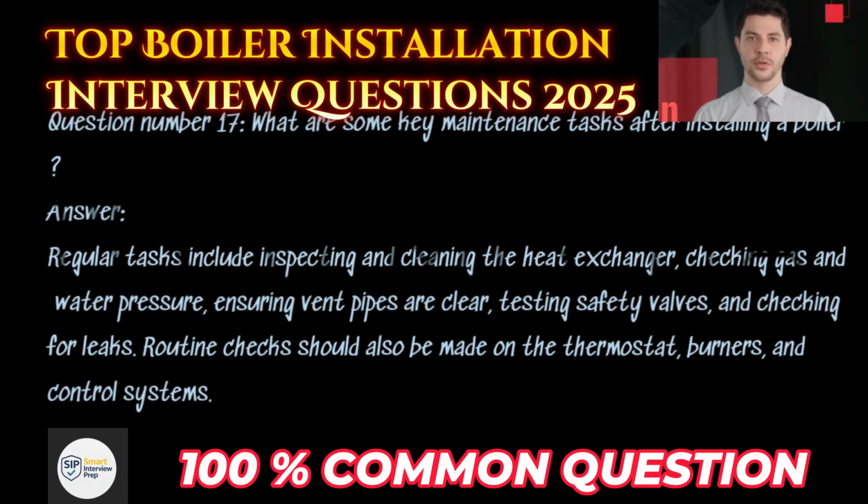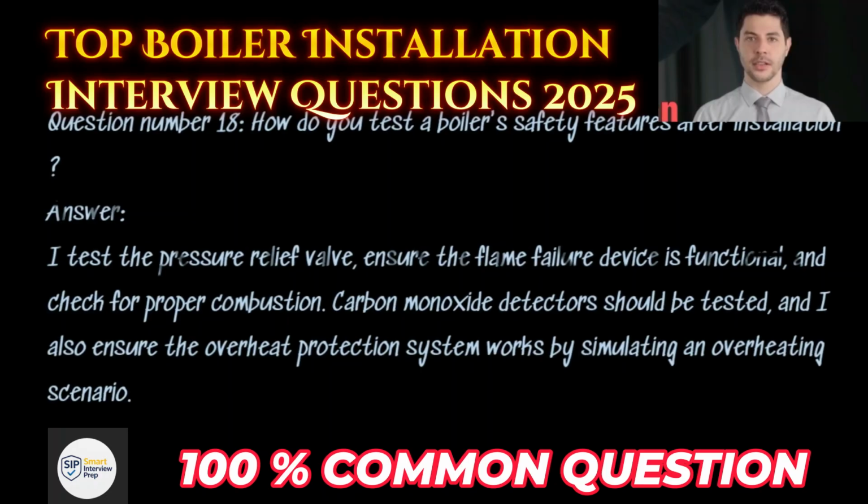Question number 17. What are some key maintenance tasks after installing a boiler? Answer. Regular tasks include inspecting and cleaning the heat exchanger, checking gas and water pressure, ensuring vent pipes are clear, testing safety valves, and checking for leaks. Routine checks should also be made on the thermostat, burners, and control systems.